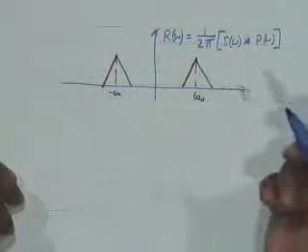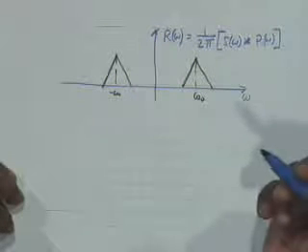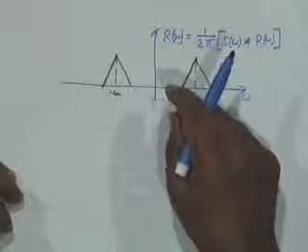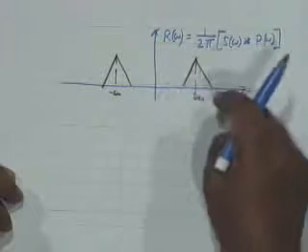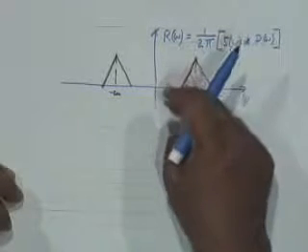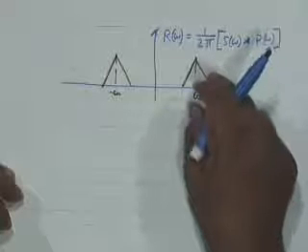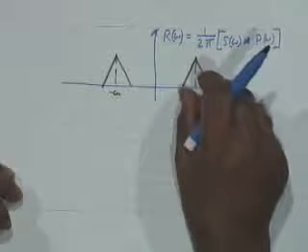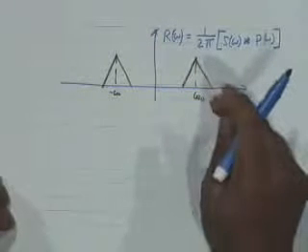And this is what we mean by modulation, that is, a low frequency is superimposed or used to modulate a higher frequency omega naught, and it is this higher frequency which contains all the information of the low frequency signal. The spectrum is intact means information is intact.